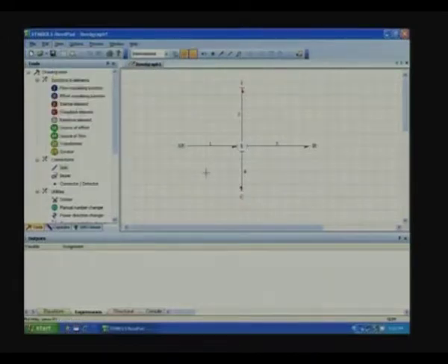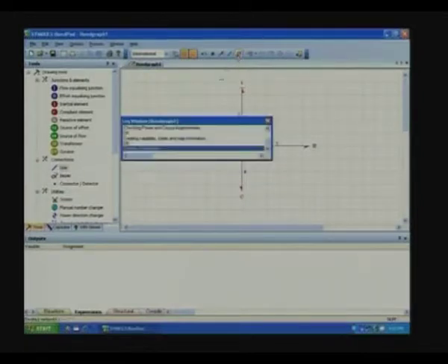So, you can see the causalities, right? AC is receiving the flow information, I is giving the flow information. So, in one junction the flow information has come, it is distributing in the other bonds, is fine. In any case that needs to be tested. So, check integrity, it says 0 errors, 0 warnings. So, we are fine.